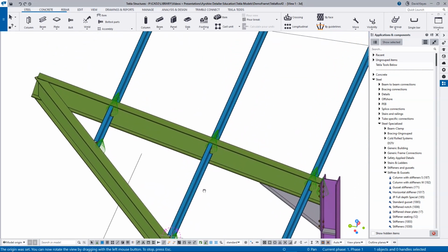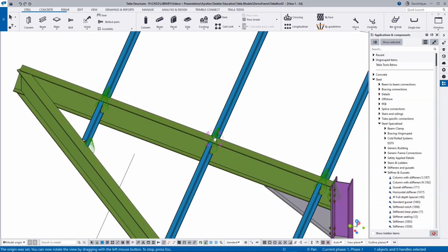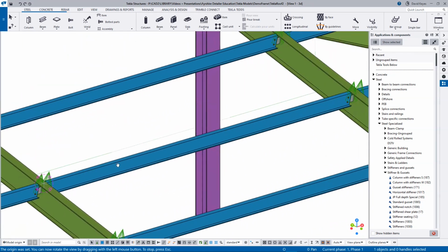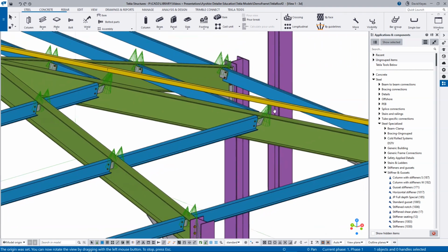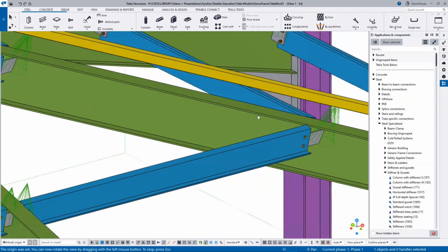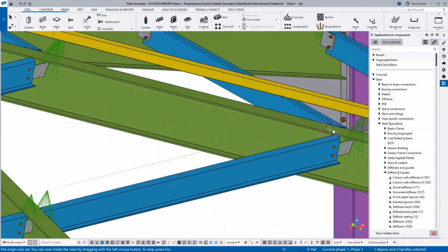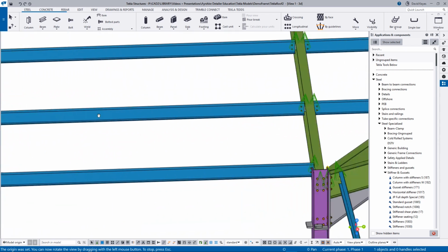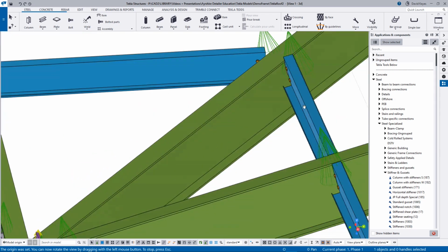A hidden use for these macros is that both can add connection plates for inboard systems, where purlins sit between rafters. Both macros can be used at all inboard conditions, including square cut and angle cut plates.